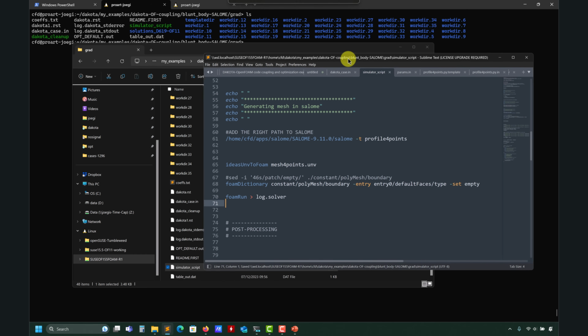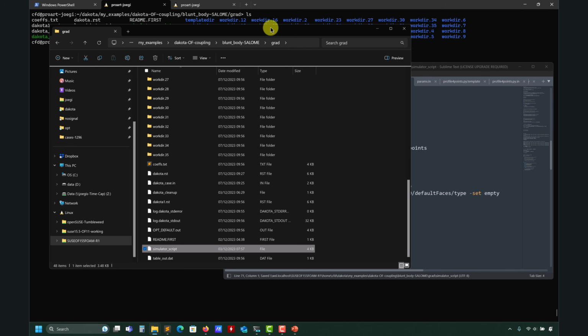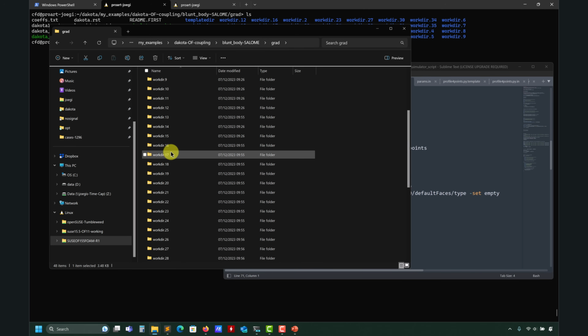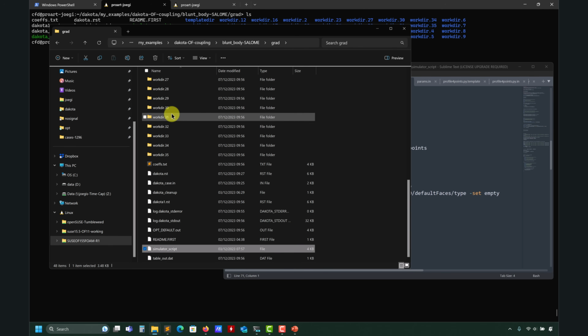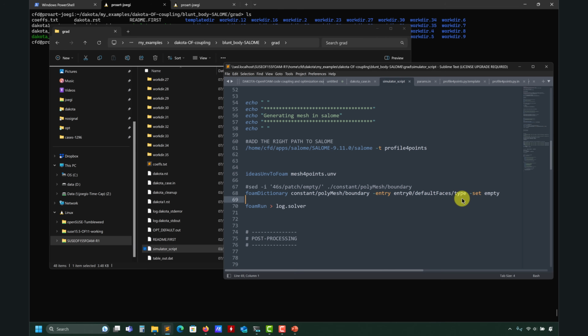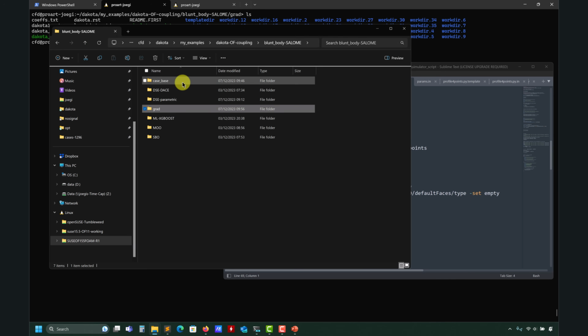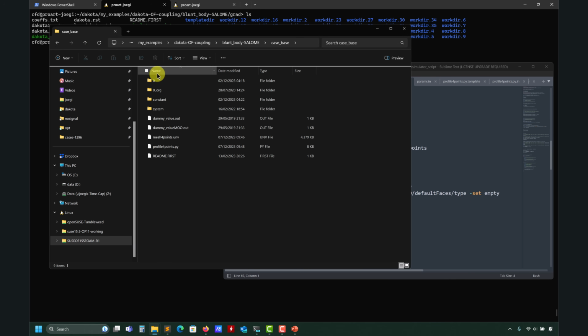And also always double check. If you're running locally, it is inexpensive, but when you move to a cluster, if you make a mistake in your script and you're missing a file, again you need to go into the queue. So always double check all your case base, your scripts, everything, so that you don't have a missing file.